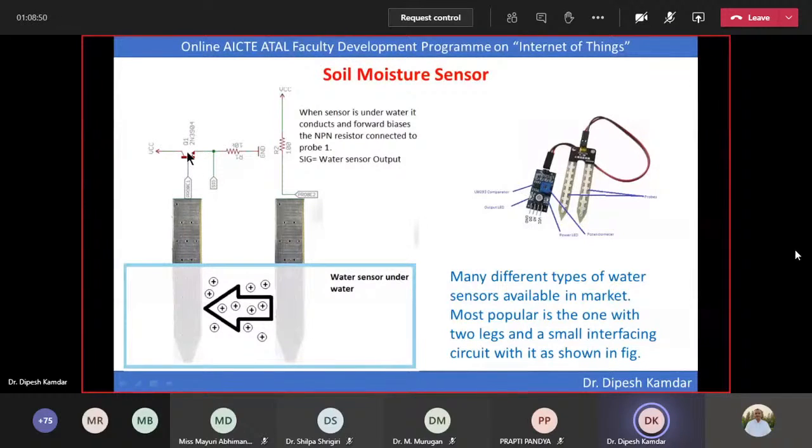From the amount of current that is able to pass through this, we can have the data here, and this data again we need to calibrate to know the amount of moisture we are having. Normally, once you find out the amount of moisture you have and set up the threshold accordingly, controlling actions can take place.